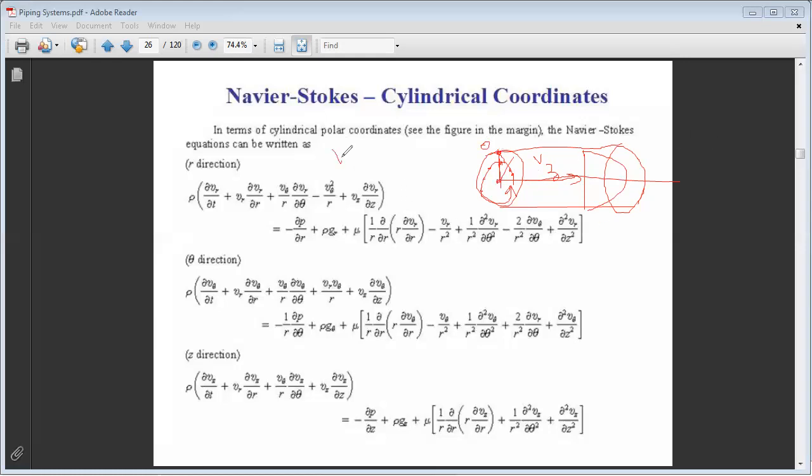So we can say the velocity profile has only a component along Z, and this Z component is just a function of R. This allows us to simplify our relations a lot. So starting from the equations, VR is 0 and V theta is 0, all of these cancel out. I have only VZ as a function of R. In this equation, I am left with these two terms: del P by del R equals rho GR. And what is GR? GR is the component of G along R.